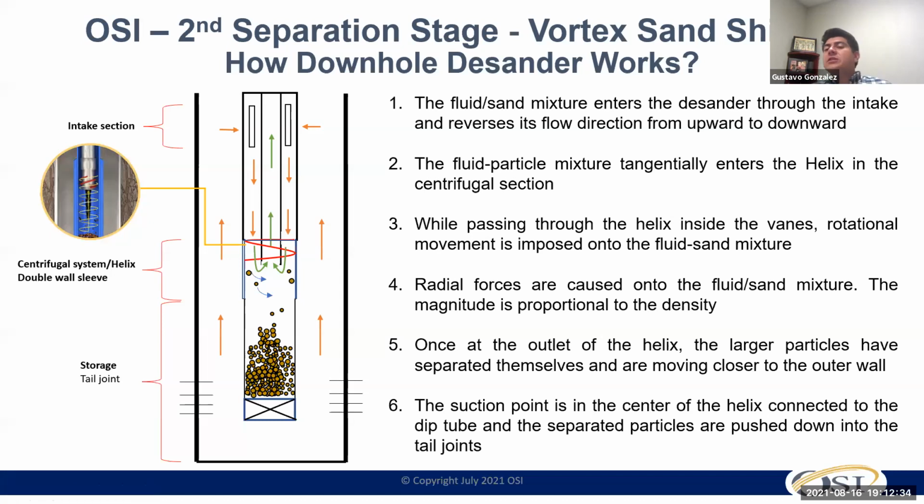Some of the issues that some operators have faced in the past, like we discussed from the beginning, is that if I don't have enough flowback and I'm putting my ESP on at day one to live with all the sand, sometimes it's how fast I can actually fill those mud joints or tailpipe. Some people have been filling those in 8 days. Some people it's taking more than a year and a half. The secret behind that is how we're operating the well, how much sand we're regulating, and the rate that I allow that ESP to produce the sand.